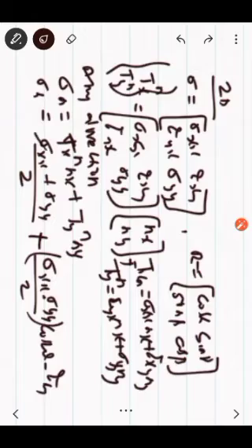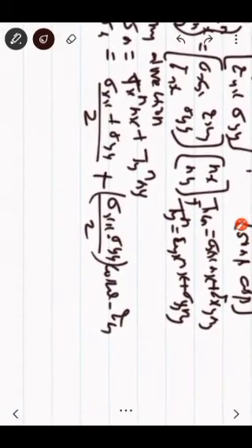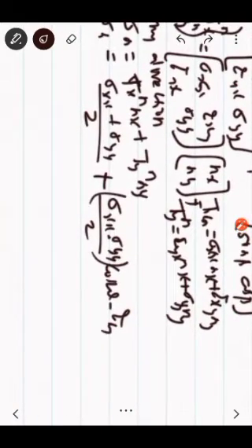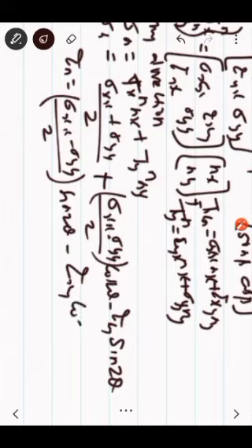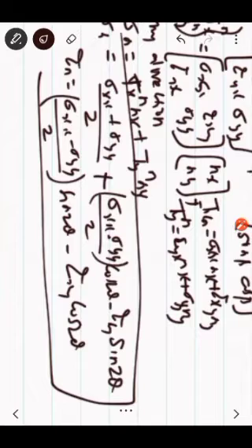If you note down these two pages, you can solve any problems. Sin 2 theta. Same way for tau, you can write tau n equal to sigma x minus sigma y by 2 sin 2 theta minus tau xy cos 2 theta. You have to memorize this formula, and this is obtained by substituting all the values from the above.